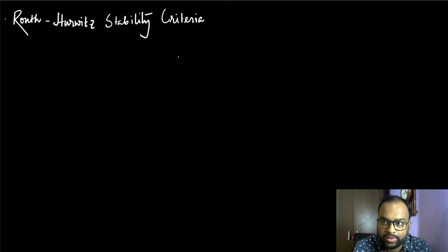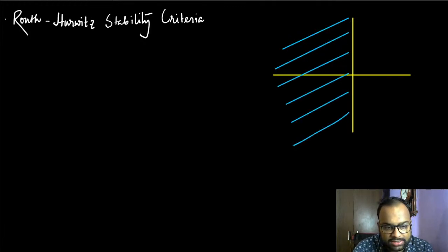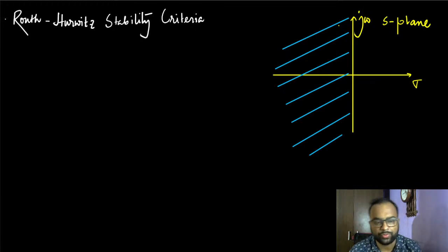And then we proved that if we have a transfer function, and we can calculate the pole locations, then we can check them, and if all of the poles have negative real parts, in other terms, if all of the poles reside on the negative half plane in sigma, essentially in the left half plane, left of the imaginary axis, in the S plane, with the sigma axis and the omega axis, sometimes written as j omega to indicate we are representing this with complex frequency terminology, if the poles are strictly there, then we say that the system is stable.